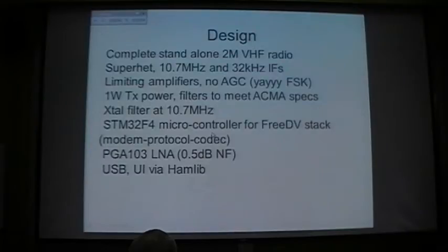It's got 1 watt of transmit power and filters that meet ACMA specs. So this is much more than your SDR dongle that doesn't have equal bandpass filters or doesn't transmit. This is a radio that you can actually use for real conversations legally and it will meet specs. It's been designed for that. There's a crystal filter at 10.7 megahertz, which provides the primary channel selectivity.